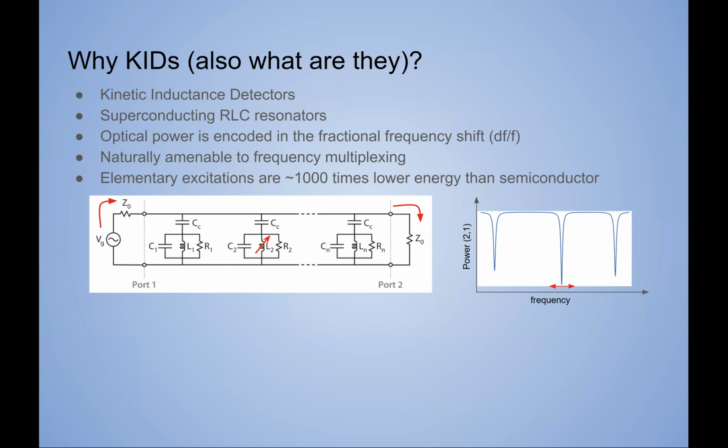Is the Q of your resonator just that R term, or is it some combination of R and C? It's basically like each one represents a loss, so you add the different losses, the rate at which a resonator loses energy through different channels. One of those would be this coupling capacitor, one would be the resistance, and they just add in parallel. Yeah, so they both determine it.